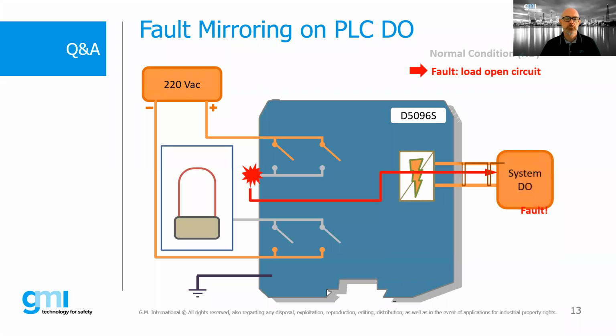This system, through an upward impedance variation of the relay input circuit, allows us to supervise and see the fault in the field. This system allows considerable savings in engineering cost, as it allows us not to use a dedicated DI card for this purpose.